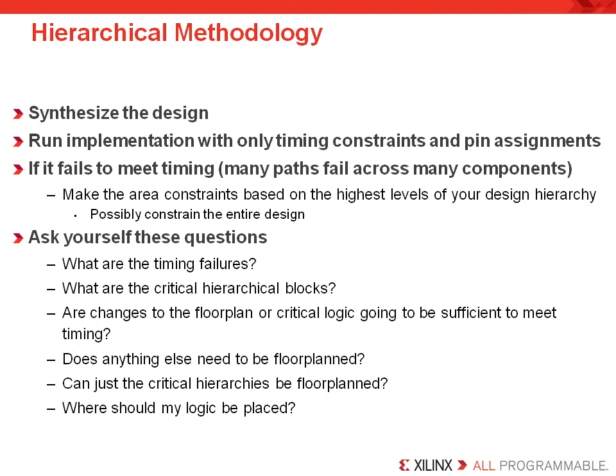The hierarchical floor planning flow is more powerful than the reuse flow. A good hierarchical floor plan can close timing on a design that has never met timing. The analysis done to create a good floor plan can suggest design and logic changes to meet timing more easily and consistently. The hierarchical floor planning flow is resistant to design changes and can close timing and bring consistency to the overall design.